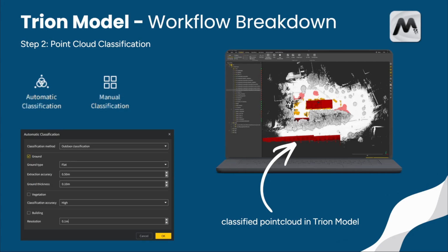For example, buildings, stockpiles, vehicles, trees, or other objects that will interfere with the terrain model. The goal at this stage is very clear. We want to end up with a clean point cloud that contains only the relevant ground points.